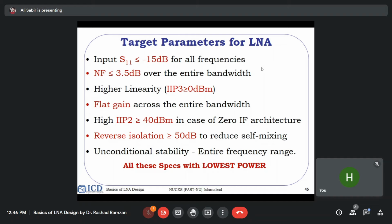Small area is becoming more important with time because now we have MIMO systems. So in a massive MIMO system on chip, we will be having say 64 antennas on a single chip. So imagine we have 64 antennas and 64 amplifiers. If amplifiers are using inductors, which is a classical way to design the amplifier, then the chip will be as big as a PCB.